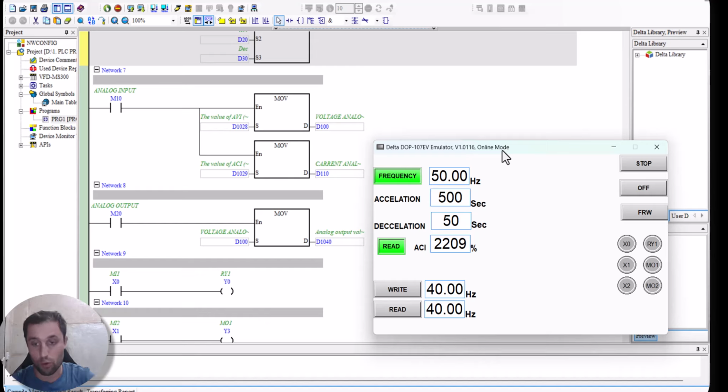So this is what you need this for. In some areas you have small logic, so you don't need to buy one PLC. You can use your VFD and you can communicate easily with HMI. So you fix one HMI and one VFD, and inside your VFD you have some logic. If you have some analog input, some sensor, you can check.